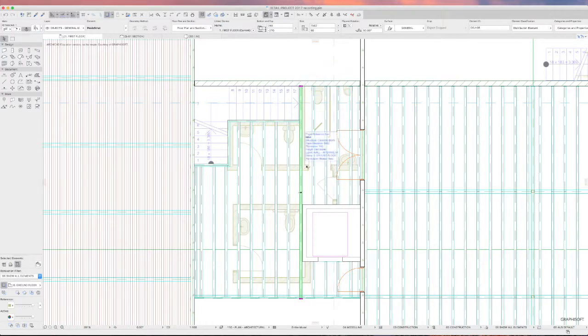And then we can just copy across 450 in this direction, closing up the last gap, and then 450 in this dimension, continuing the 450s, closing off the last gap. Then I just placed a joist on top of this block wall at this point to trim the floor back to around the stairs. I've got a trimmer sitting on top of this block wall here, which will also enable these joists to trim into. Other than that, it's a pretty simple floor joist layout.